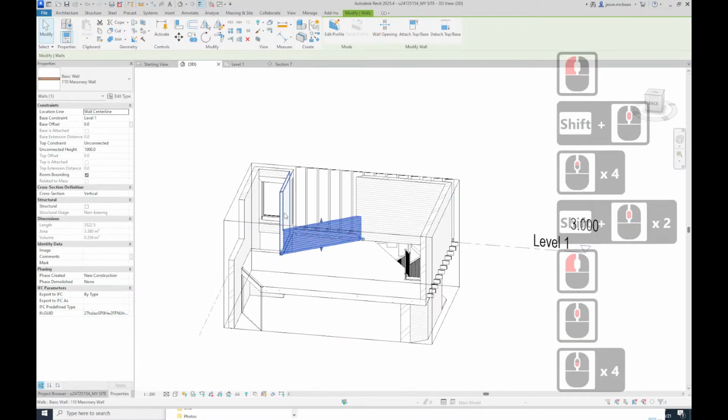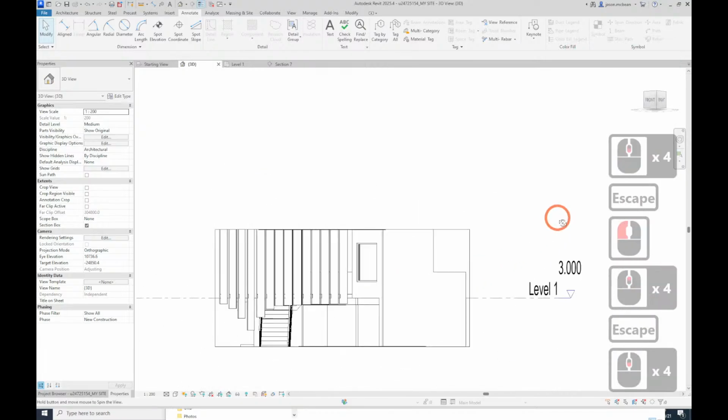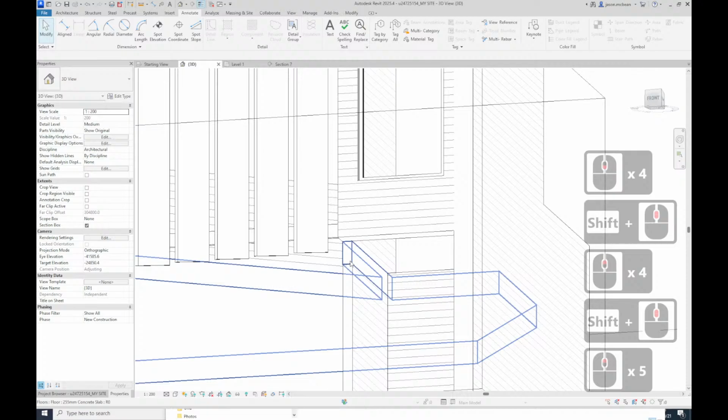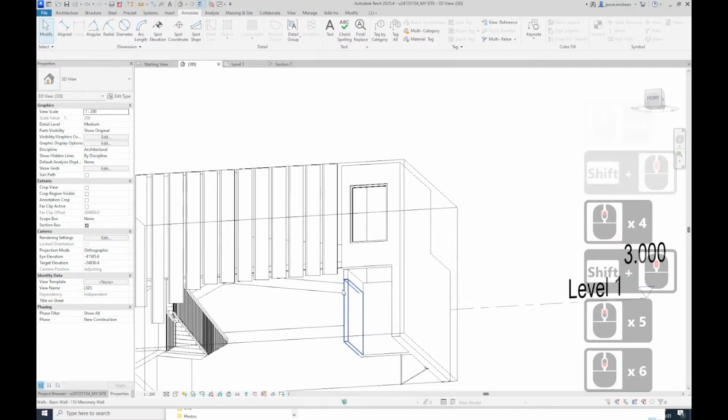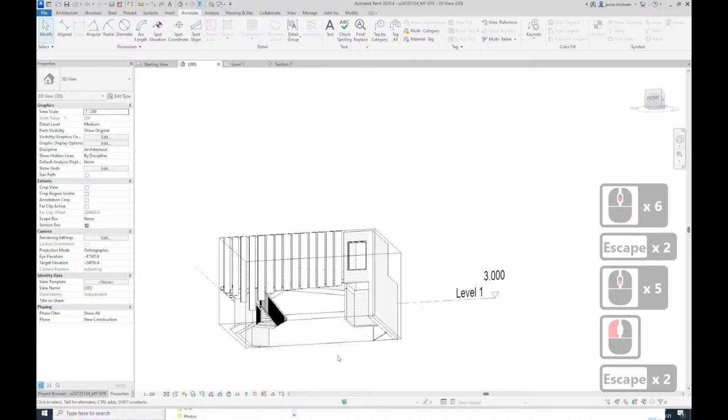Okay, so all of these walls work the same. That wall, yes, but this wall maybe, that's fine. If it has to go to ground floor, you tell it to go to ground floor or not. You don't want to have all these stacking walls because things start getting misaligned. Things start going awry. Walls that need to go straight through, you take them straight through. Walls that stay from level to level, they stay level to level.